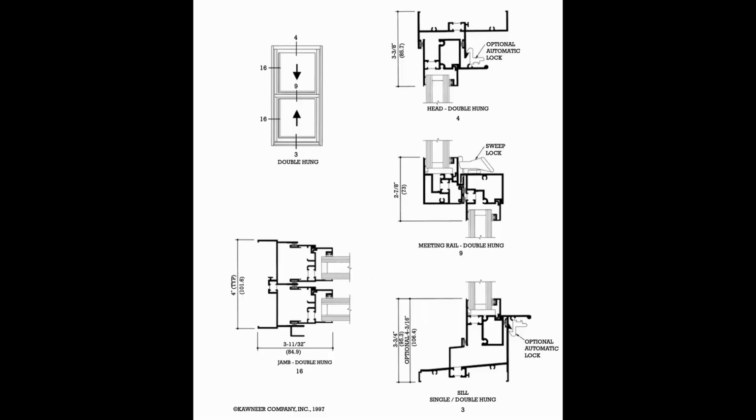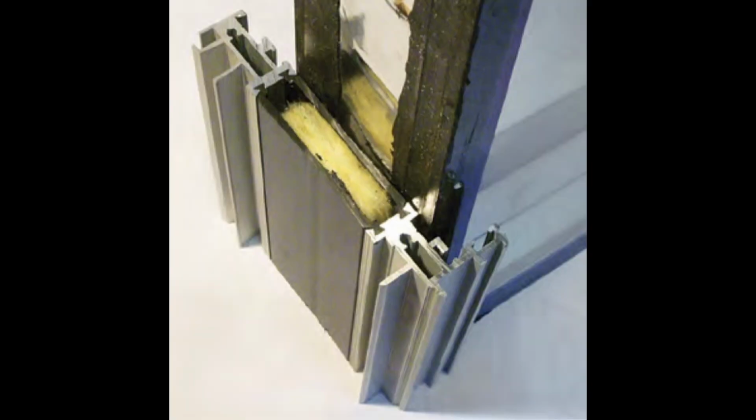Moving on to aluminum windows, the material itself, when it is used in window construction, is strong and less vulnerable to moisture damage in relation to wooden windows. The good thing about aluminum windows is that durable factory finishes can eliminate the need for periodic repainting after the window is installed. Going back to the wooden window, it might need a touch up every couple of years, but aluminum does not need that because durable finishes are applied to the aluminum in the factory.